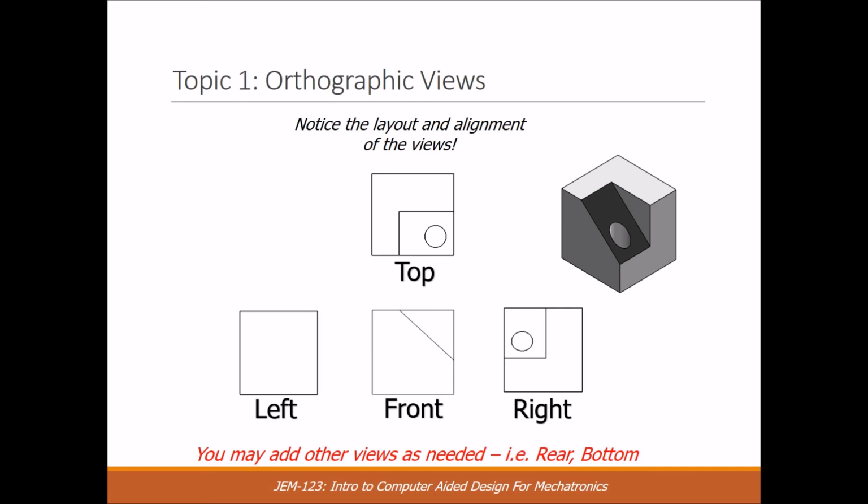You can take away views. You might not even want to have that left view because it does not add much information. If you had a part where the bottom has details on it that you wouldn't see in these 3 or 4 views, you may add a bottom view or a rear view.